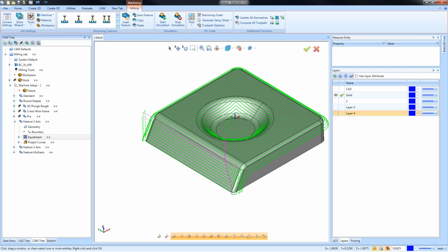Okay, so again, it depends on whether you're making tooling or the parts themselves. But the scallops that are left based off of this pattern, you can tighten it up and it'll give you a good finish. But because you're changing direction a lot, those changes of direction will show up in your parts. Okay, so Equidistant, detail, more catch-all.